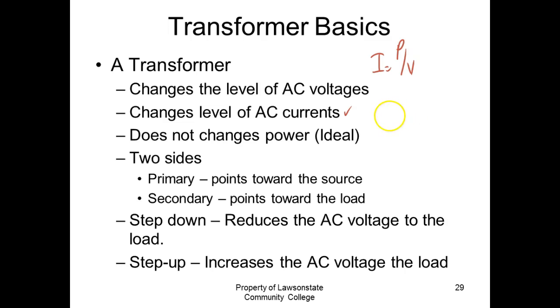Now, of course, what we're going to need this for is that normally when we deal with power, we put something that protects the power. So we got 2 options. We can put a fuse right here. Well, actually, we got 3 options. But the problem is, most people will want to rate the fuse for the secondary and not the primary. So the transformer will flat burn up. Right? You understand that? And the fuse will never blow because you're rating it for secondary current and not primary.